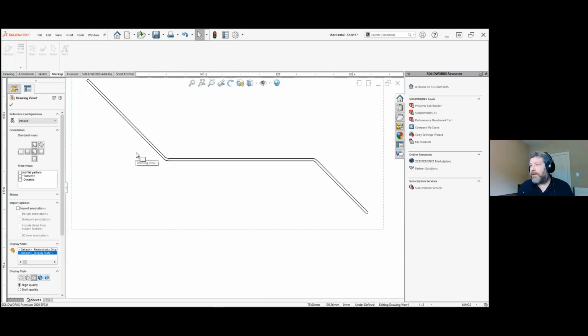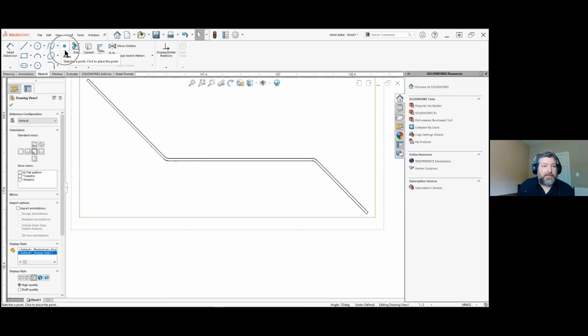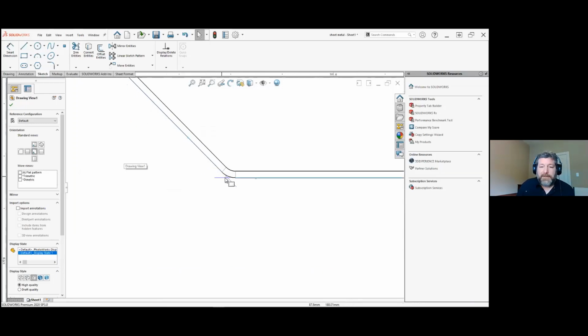Okay. Another thing that I wanted to show back here at the drawing level is the idea of a virtual sharp. There are only a few things now in SOLIDWORKS that require things to be pre-selected. So I'm going to select on that edge and select on that edge. And then from the sketch toolbar, I'm going to come over and hit the sketch point. That's the shortcut, if you will, to add a virtual sharp.